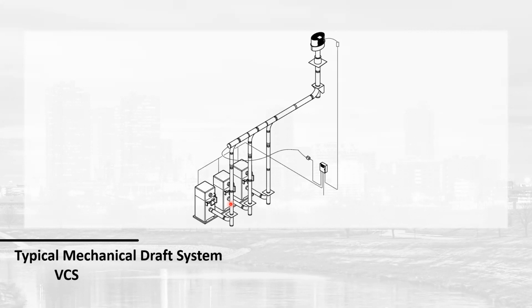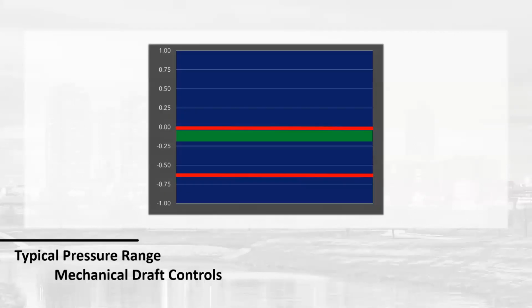It's either that or a temperature swing issue. But point being is, in that scenario, the only way that you can overcome that is to oversize this stack, so you have more volume, which means that that change is affected less, or put in a control system that can handle plus or minus 1 inch, which is what we do. And again, if your set point's here, you don't have a lot of range.